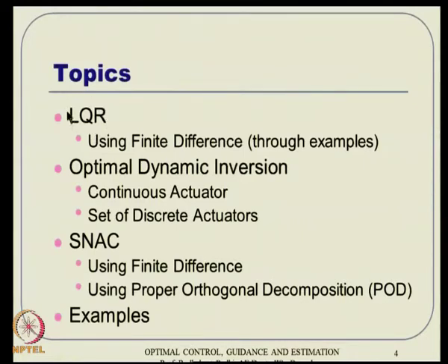Okay. So, this is how it is, and the topic that these two lectures will talk about is LQR design. If the system dynamics happens to be linear, that means the PDE itself is linear, then it will result in an approximate lumped parameter system which is also linear. And the cost function is quadratic, so it also results in a finite dimensional cost function which is also quadratic. So, that will have a compatible LQR formulation, and because we know the LQR formulation, we can go ahead and solve it and implement it through the Riccati equation, all that. So, we will not talk about philosophy here, we directly know the philosophy. I will just demonstrate this idea through one example, so your ideas will be clear actually.